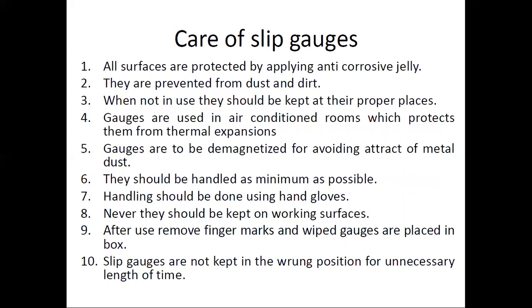Now, care of slip gauges. One 3 marks question should be asked on this topic: what care should be taken while using slip gauges? Let us see. First, all surfaces are protected by applying anti-corrosive jelly. The surfaces of the slip gauges are applied with anti-corrosive jelly, so they are prevented from dust and dirt. As I already told you, this is important because the presence of dust and dirt particles will reduce the efficiency of gripping.